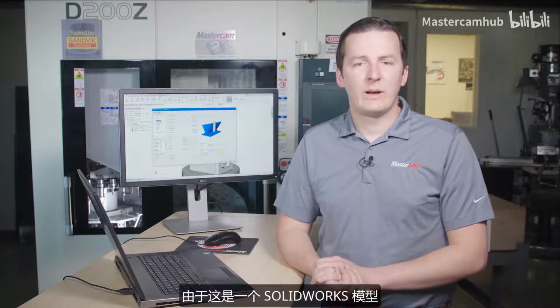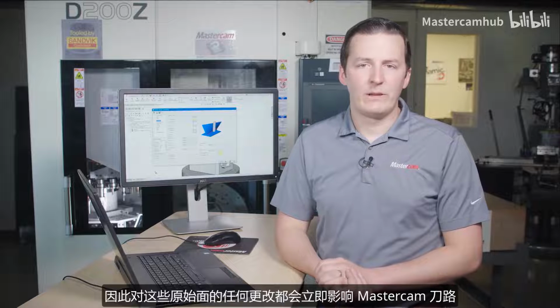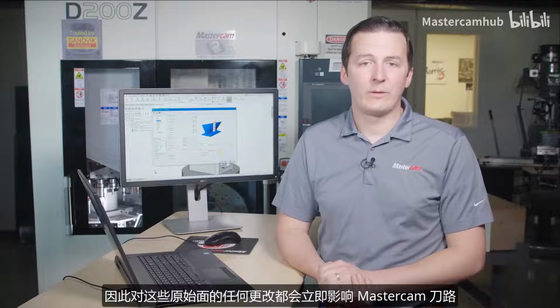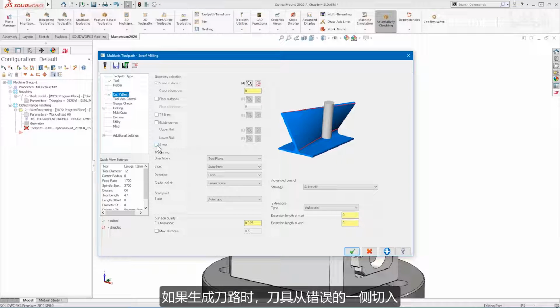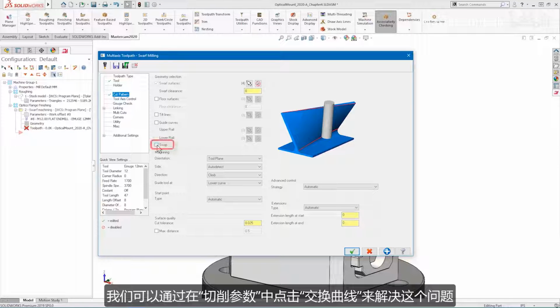Because this is a SolidWorks model, any changes to these original faces will prompt an immediate change to the Mastercam toolpath. If the tool is cutting from the wrong side when the toolpath is generated, we can correct this by toggling the swap checkbox in the cut parameters.